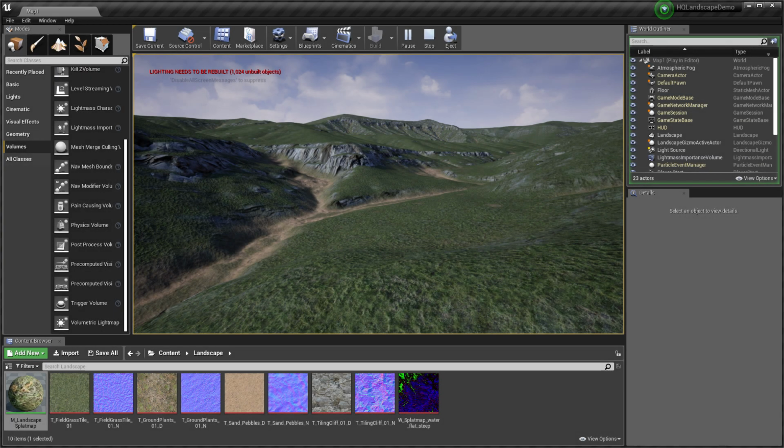You may at this time wish to go back and adjust some of the splat map material setup. I recreated the extractor for the flat slopes at settings of 1790-10. I recreated the splat map and re-imported it into the engine. I also adjusted the material landscape coords to dirt 10, path 10, rock 50, and grass 10. This is what it looks like unbuilt.